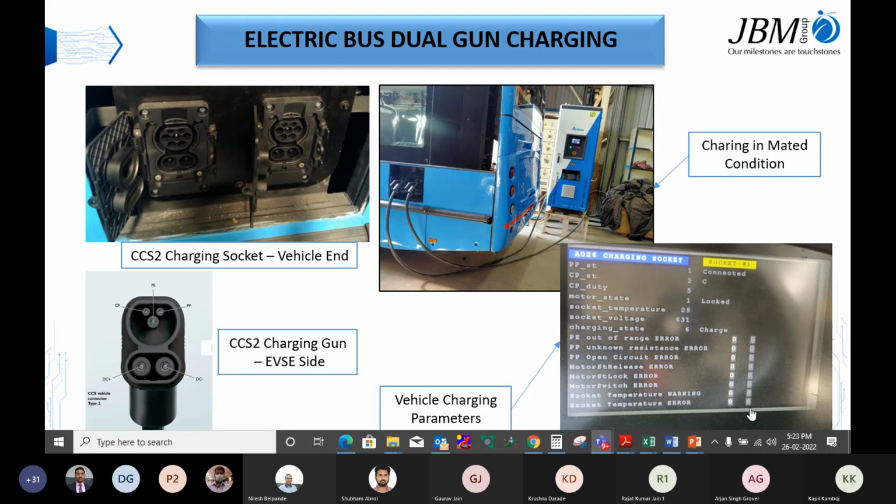So based on that, if there is any insulation failure, what will happen? What will be the issue? It will not go to the pre-charge stage. It will stop the charging as it is. So it means up to the PDU, it will detect the failure. Before the charging contactors, it will check the insulation up to the charging contactors in the PDU. So if there is any failure in the line, it will stop the charging before going to the pre-charge state.